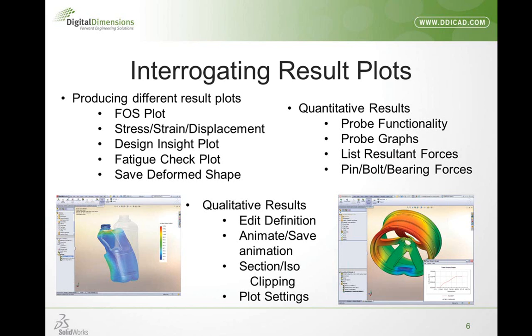Also, if you're using assemblies, as I mentioned earlier, we can virtualize and idealize our model. We can take an assembly with different bolts, maybe a bolt pattern, and remove those fasteners from your study and replace them with virtual fasteners that we can model in simulation. You can get information from those virtual bolts and see if your fasteners will pass or fail a particular loading instance.